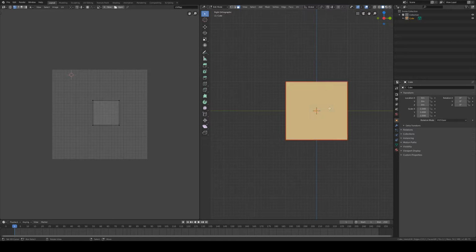another way that you can do this is if we select all the faces and hit Smart UV Project. This will open up a small menu, and you can change these values. This will disconnect every single face for you so that you don't have any connected objects. The problem with this is that sometimes they're not weighted well and small faces end up taking up more space than large ones. It works well for the most part, but sometimes you'll get really pixelated faces, especially if you're using smaller texture sizes. So you can see here we got these 6 faces.